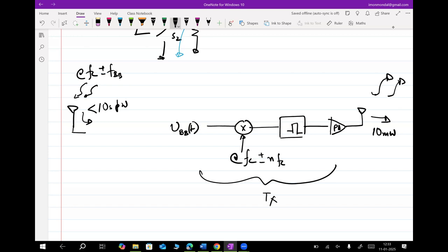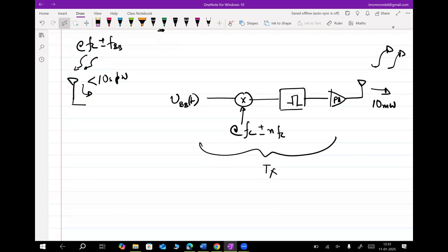That's why in RF lingo, dB is almost always the unit of choice. Now dB is essentially a ratio. Just saying a dB doesn't mean anything unless I say what I am comparing with. I can always take a number and do a dB of it, 10 log something, but what is that dB?